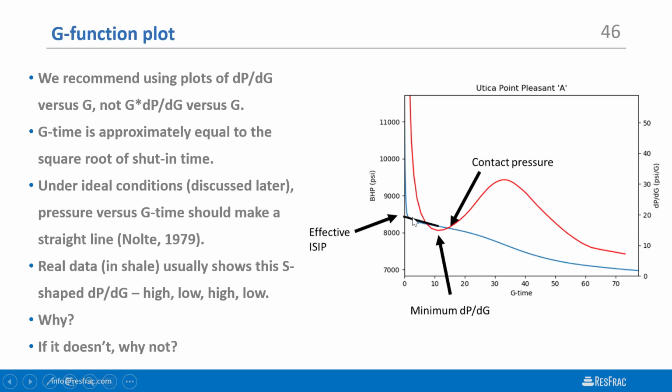If that happens, what you might see is the pressure could flatten out to a really low derivative and then just stay really flat and high for a really long time. If that happens, maybe there really truly was a total seal off. But that's not most cases. Most cases, this dissipates. And so when we get out to about this part of the transient, we're as close to ideal. We're as close to the Nolte-Castillo optimal situation as possible.